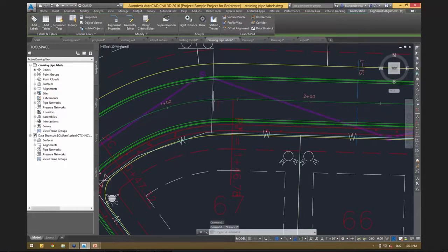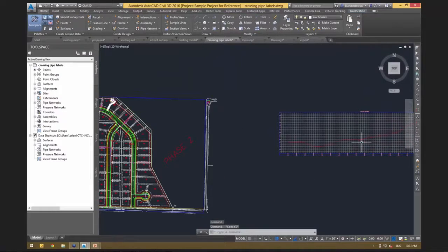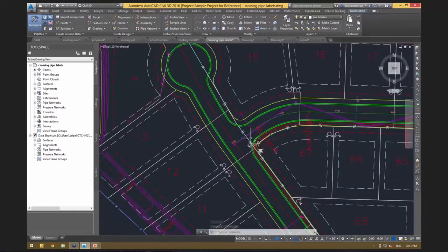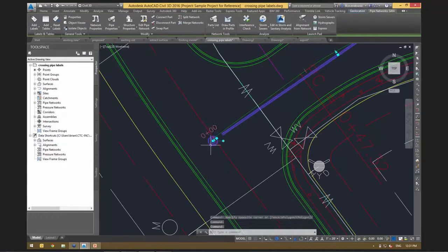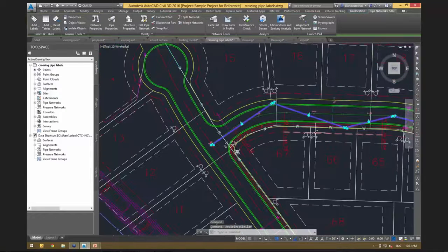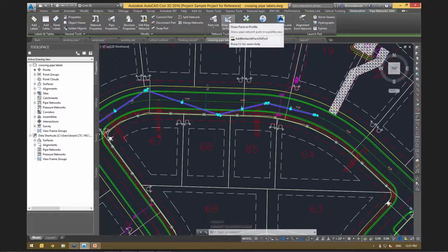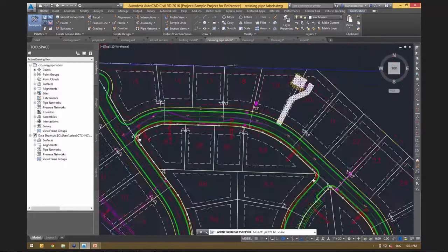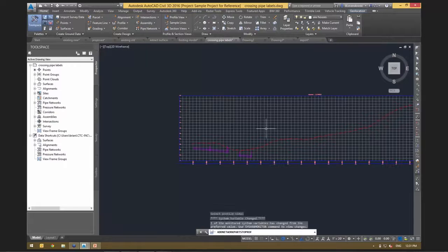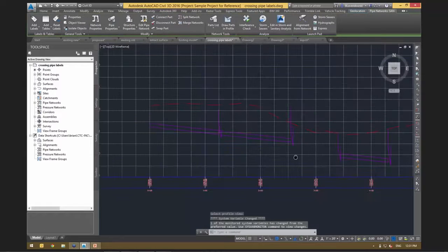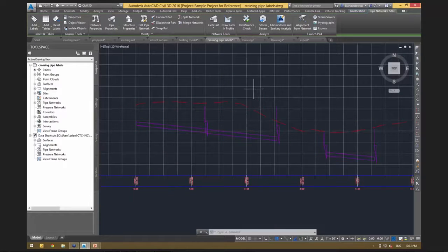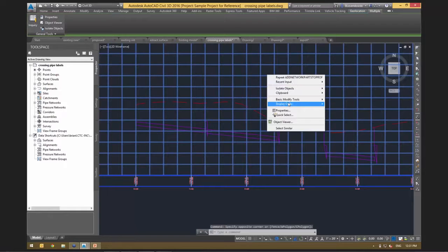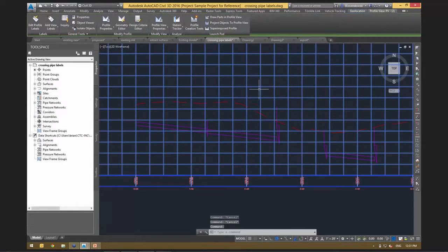But so what we're going to do, we've got a profile view over here, and we're going to project these pipes and these structures to profile view. So one of the best ways to do this is you grab the pipe and the structure, you do select similar, we have draw parts in profile, and it prompts me to go select a profile view. I can pick this, and now everything comes in there. But this is now seeing pipes coming in and out of the page here. So a standard feature we have to do here to see just crossings is to go into the profile view.